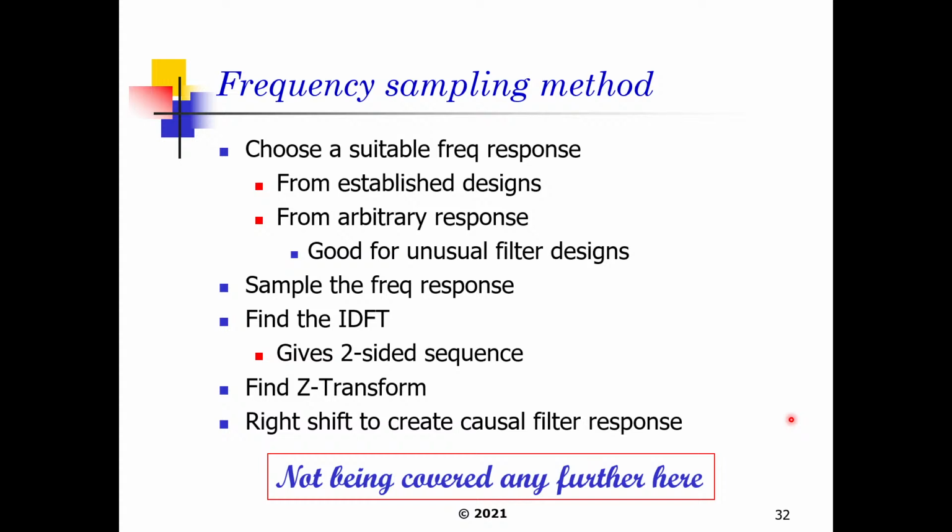And in order to mitigate this aliasing effect, we need to apply a window technique on top of the FIR filter design in order to ensure that we eliminate these unwanted frequency components as a result of spectral leakage. We also saw that in doing our filter design technique, we need to ensure that the sequence is symmetric. In doing this, we start with the ideal low-pass filter response.